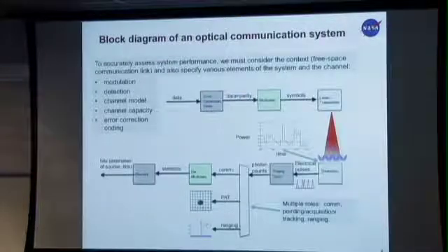Okay, typical optical system. Basically, if we're going to communicate reliably, we're going to need an error correction code and a decoder. Whatever we've coded, we need to modulate it and demodulate it, transmit it over a channel, whether that's deep space with a little bit of atmosphere coming near Earth, to a detector and some systems for synchronizing to what you did and possibly even pulling up other information like ranging information, and eventually making estimates of the data you put in.